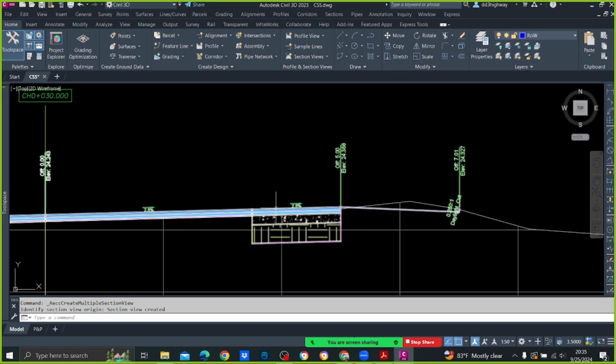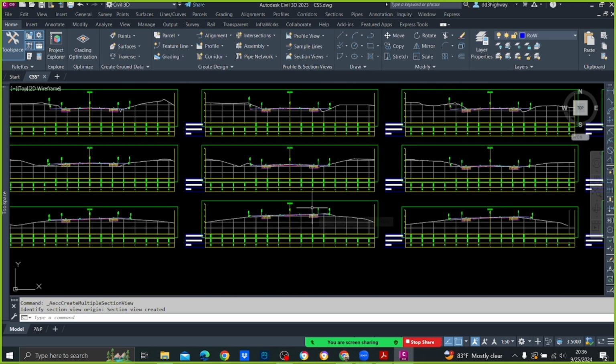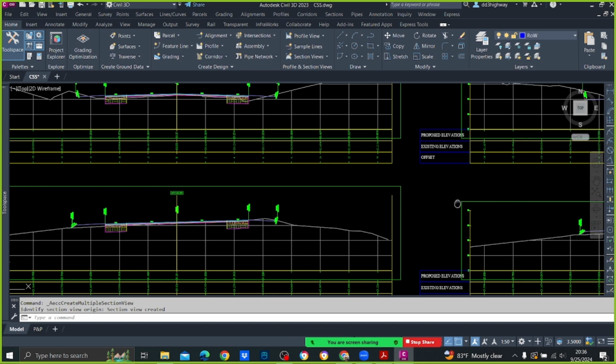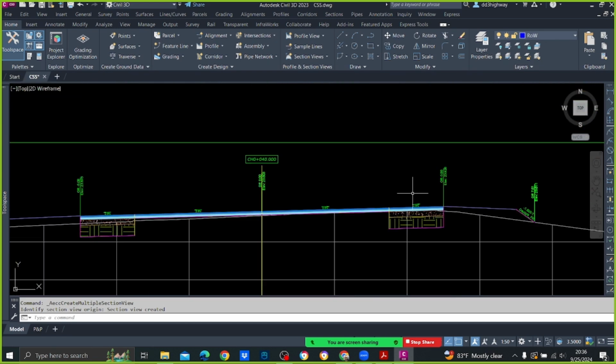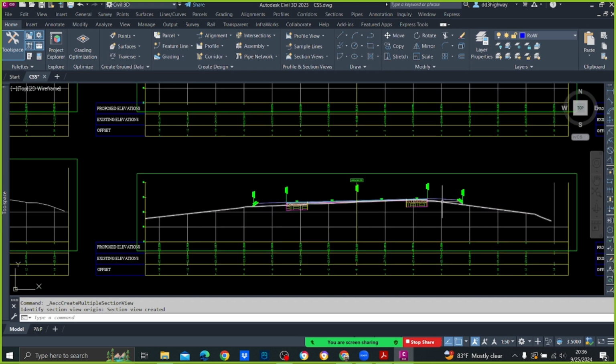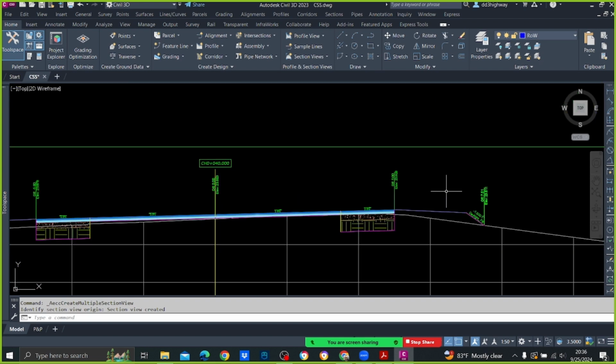Now can you see that here this is super elevated and this soft shoulder is not going into plus 2.5, instead it is coming to 4%, the other way around. Okay, that is the maximum breakover. That is what they are meaning by maximum breakover. Okay, here you can see everywhere there is super elevation, your soft shoulder is turned other way around.